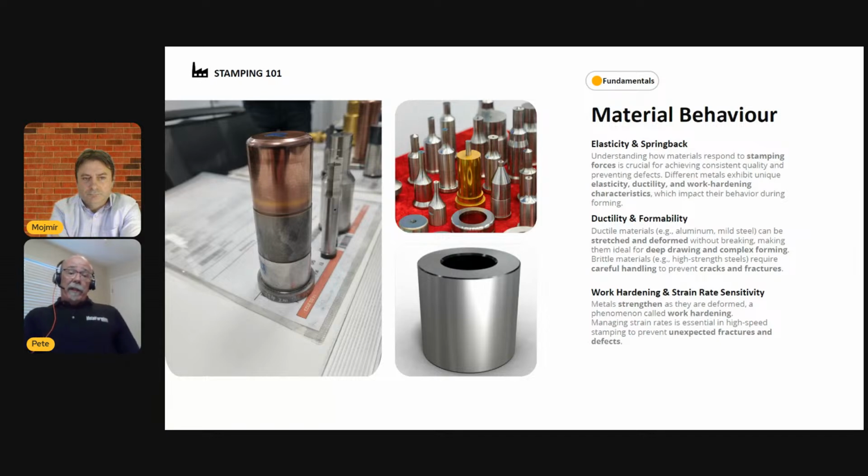With the advent of some of the advanced high-strength materials that are in the marketplace now, studies have shown that some of these materials require 15 to 17 degrees of overbending in order to get a vertical angle after forming because of the high amount of spring back. That, my friends, is going to change how you design your dies, right? We can't approach these new materials with the same guidelines and the same experiences that we have with mild steels or the traditional high strength steels.